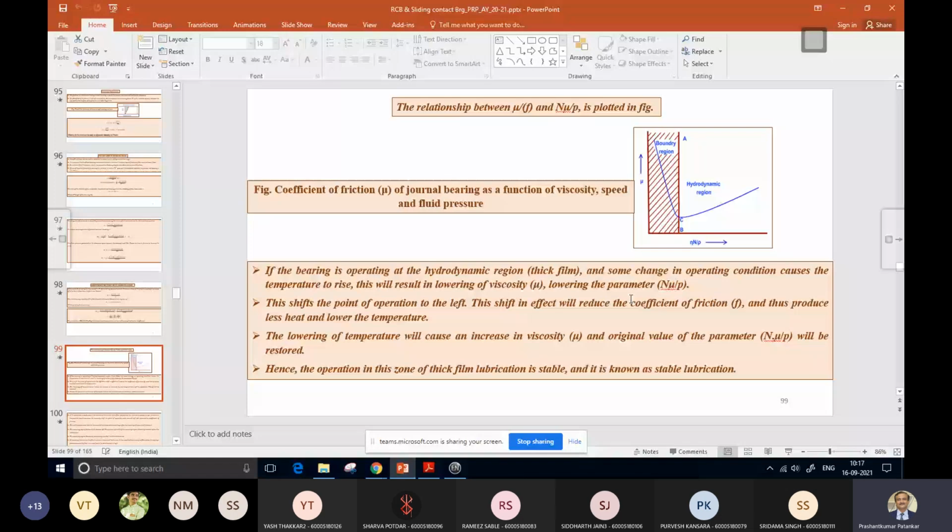Over that you have to provide fins to increase the surface area. That is one arrangement that we usually make. Or else we have to make sure that whatever lube oil we use is cooled by some means. In some cases they suggest using an oil sump from where the lube oil is pumped.